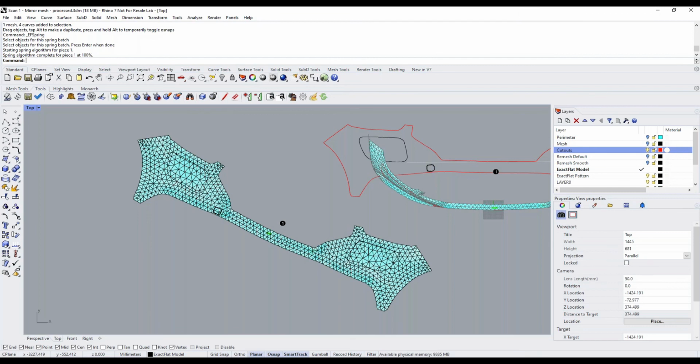If I'm scanning a front bumper, hood, and fenders to wrap using printed graphics, how can I check my graphics will line up on all the parts before printing? Well, that's a great question too, Alex. So the graphics have to flow. We call the flow between one panel or one pattern piece and another pattern piece. They have to flow accurately and be perfect. And you can check that by doing what we call walking the pattern.